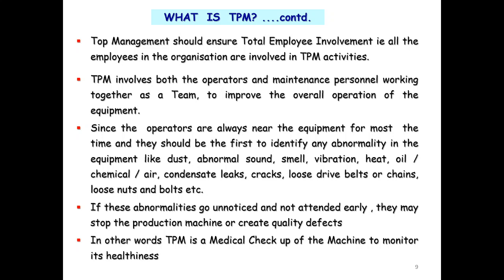The operators are the backbone in TPM since they are always near the equipment for most of the time, and it is very easy for them to identify abnormalities in the equipment such as dust, abnormal sound, odor, heat, vibration, leaks, cracks, loose or dry rubber belts or chains, loose nuts and bolts, damaged motor earthings, etc. If these abnormalities go unnoticed and not attended to in time, they may lead to breakdown of the production machine or lead to quality defects. In other words, TPM is a medical checkup of the machine to monitor its healthiness.